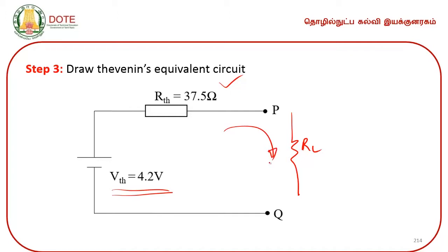So, the main idea of implementing Thevenin's theorem is, if you have n number of loops, say for example 7 or 8, you could not implement the mesh method or nodal method or Kirchhoff's voltage law straight away, because it is cumbersome. Instead of that, you can replace all the voltage sources by a single voltage source called the open circuit voltage and a single resistance called Thevenin's looking back resistance, which is connected in series with the load resistor to calculate the magnitude of current. So, it becomes as simple as that.